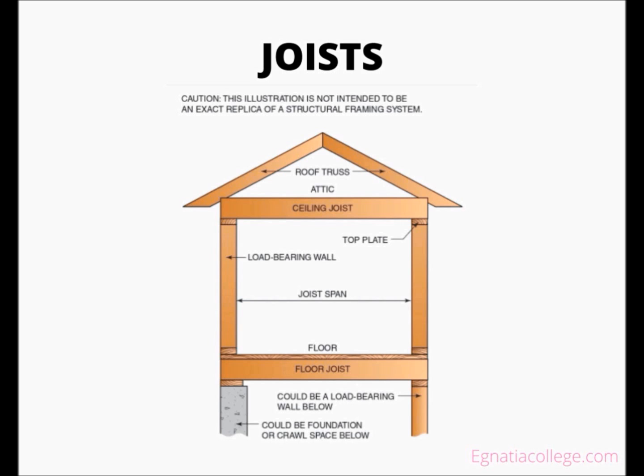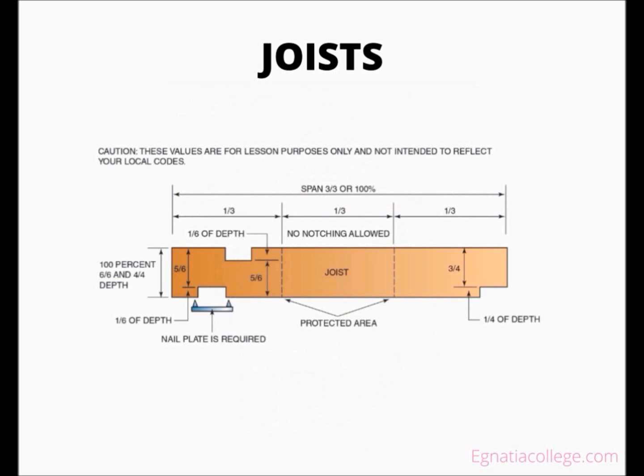The defining terms of length, width, depth, and span are used when installing wood boards. A board used vertically to erect a wall is called a stud, and that same wood board used horizontally is called a joist. The dimension of a board known as the width for a wall stud is called the depth for a joist. The length of a wall stud is known as the span of a joist.